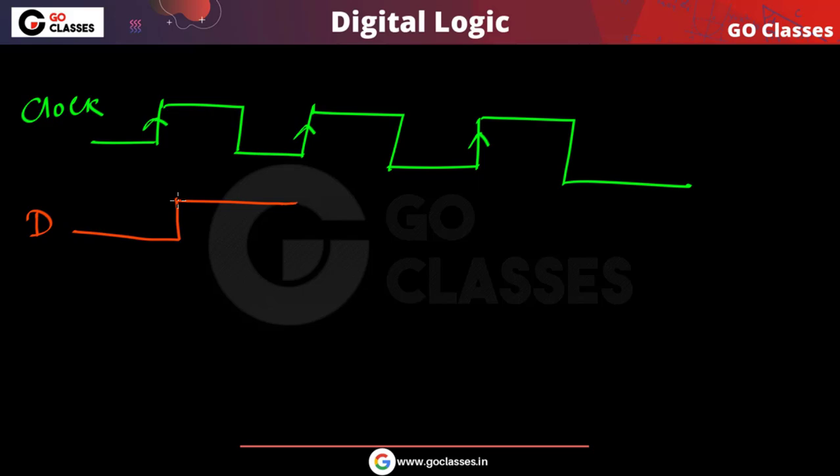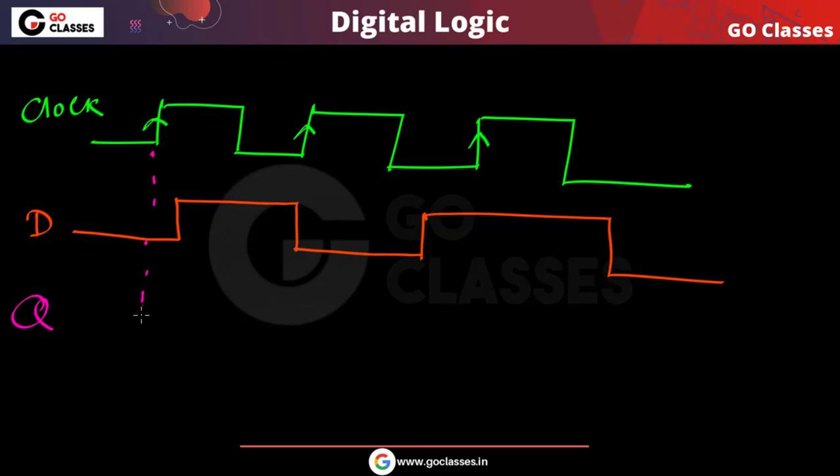So here you can notice the input signal D is like this. Let us assume. Now you can notice one thing, very simple: what will be the output signal? Initially I don't know what the output signal is, so let us assume that the output signal can be anything. I don't care about it. This means that initially Q can be 0 or 1, I don't care. Let us assume that initially Q is 0.